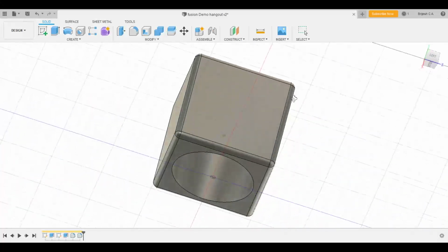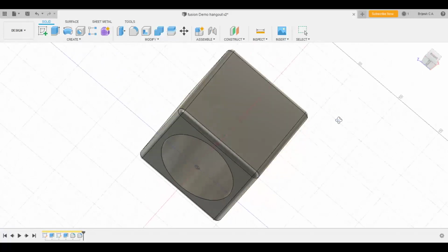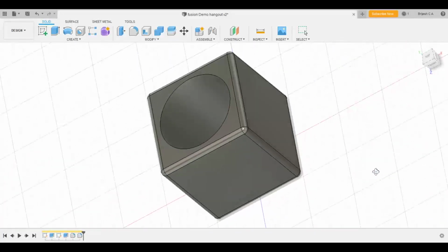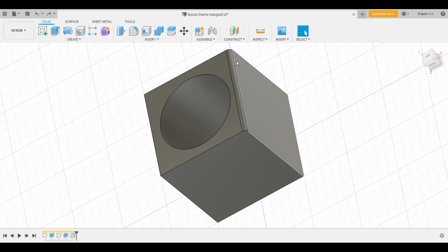Now you see this? All the edges are 5 mm. Or I have another option, I just go back. When I did only one surface or one edge, I click on this, right click and click on edit feature, and here you see this thing called edges or faces of feature selected. Here I'll select one.